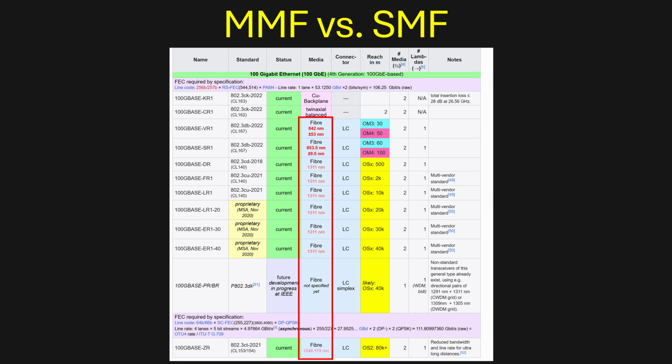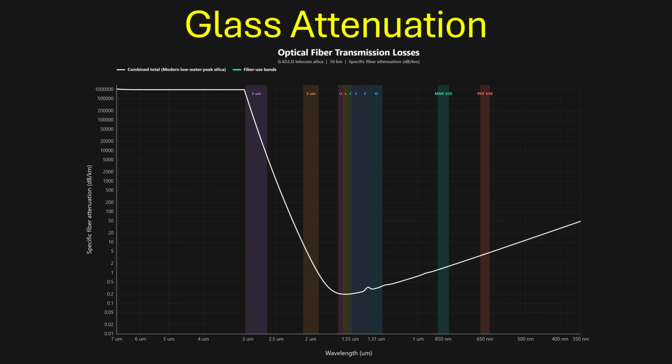Another trade-off in optical cables is which wavelength of light to use. Multimode fiber typically uses 850 nanometers, and single mode fiber uses a wider range, usually around 1310 nanometers or 1550 nanometers, for very long distance cables. These wavelengths are also common for laser links in space. Once again, this is due to a trade-off between performance and transceiver costs.